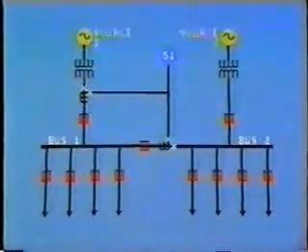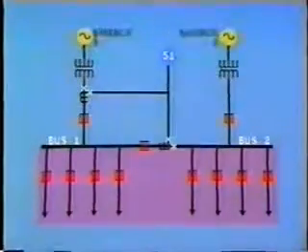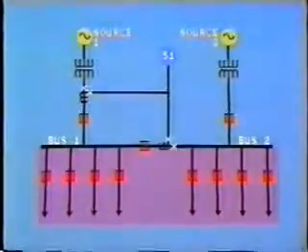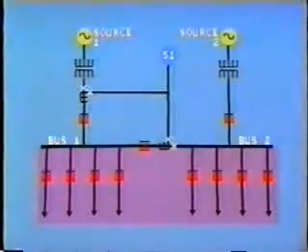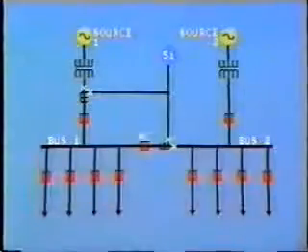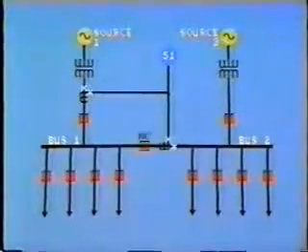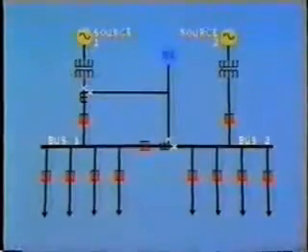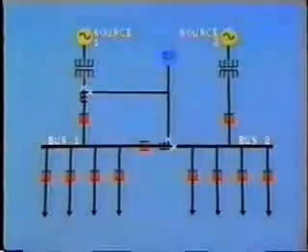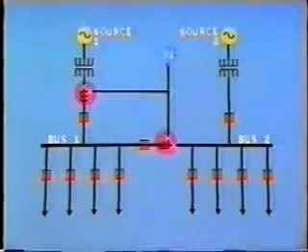The buses are fed from 2 separate sources and feed 8 outgoing radial feeders. As the feeders are radial, the current will not reverse in the case of a bus fault. On this particular system, the bus tie is normally closed. Partial differential protection for bus 1 is provided by the time overcurrent relay 51 connected to these 2 CTs, which are in parallel.